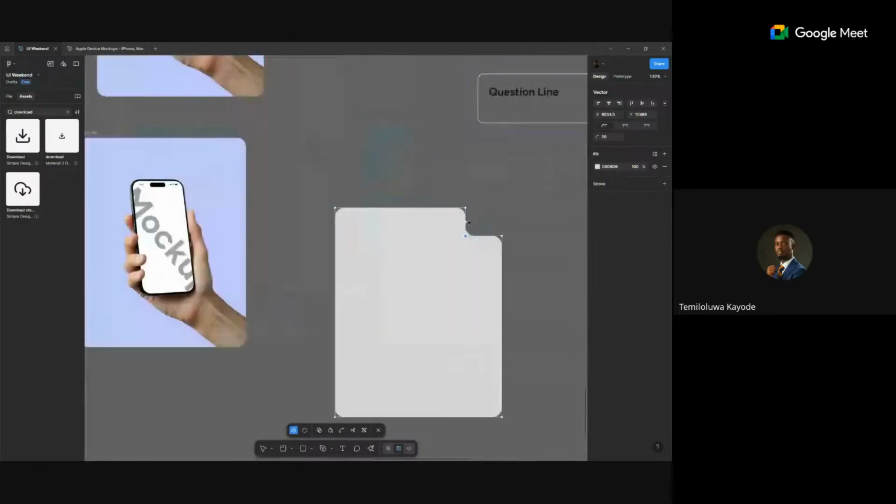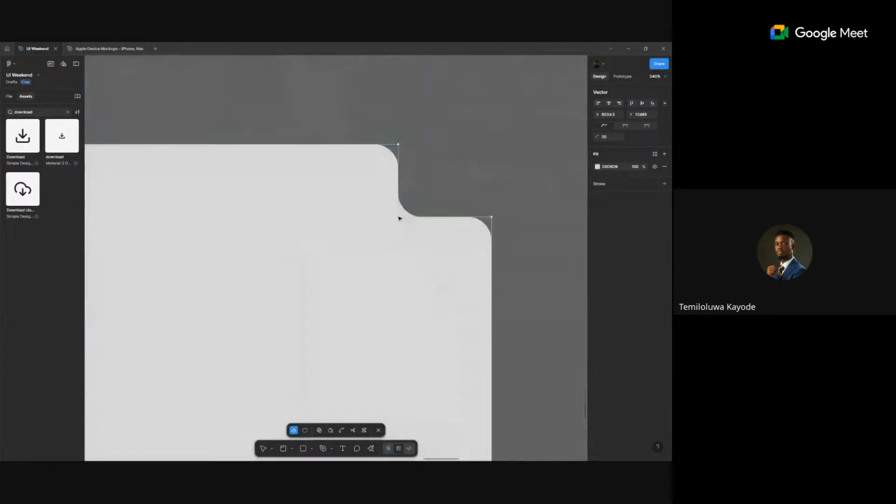So you could measure it. Once you click on a node and hit the Alt key, you can see this is 61, this is 78. You could say, I don't want 78, so you could select these 2 nodes and drag it forward using your arrow keys. Check it again. So this is 61, but 60.5.